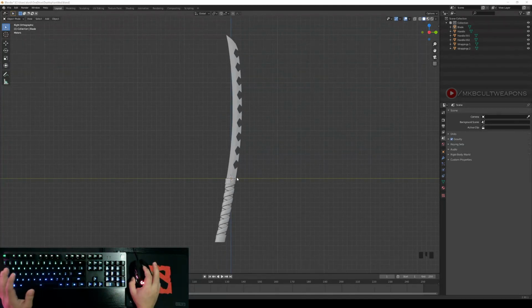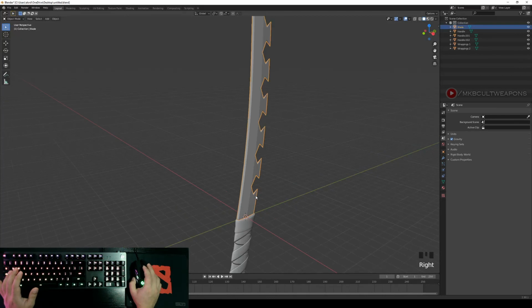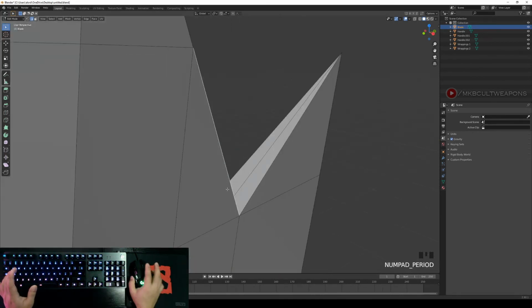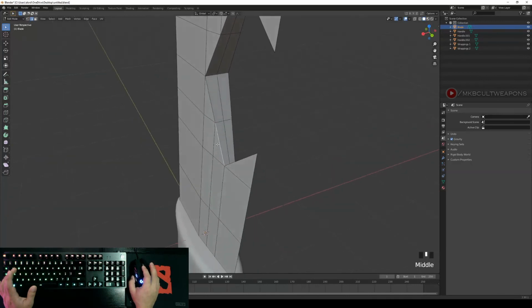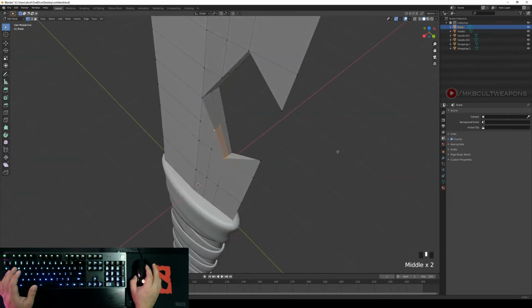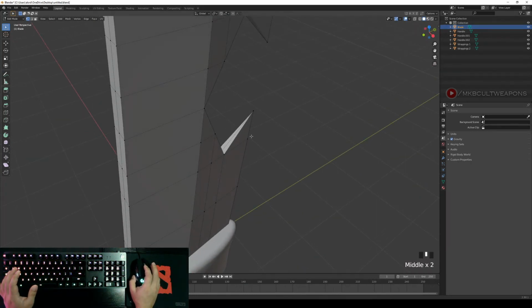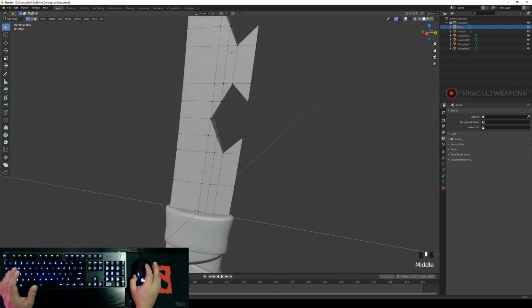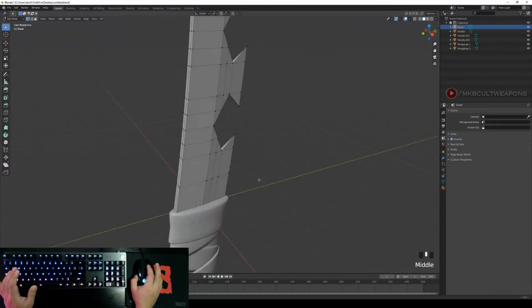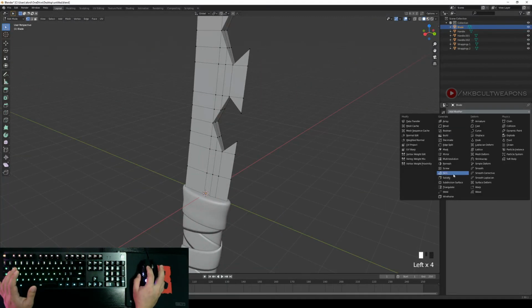There are things I need to address before I end this video. Actually, I did not teach you how to do the mirror modifier, wherein that will be much easier. I taught you how to do the stitching pattern. I think I will call that stitching pattern, wherein we fill things up whenever there's a hole over here. We just select and press F to fill those little gaps or little empty spaces there. And we did it at this side and over this side, wherein actually you could do just a single side and just do a mirror modifier.